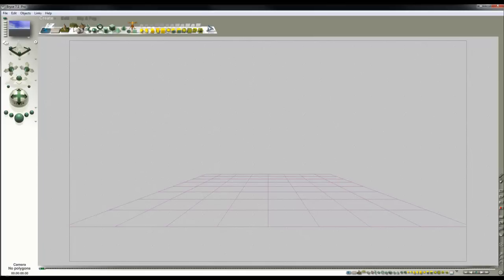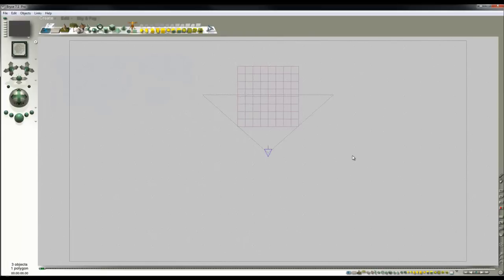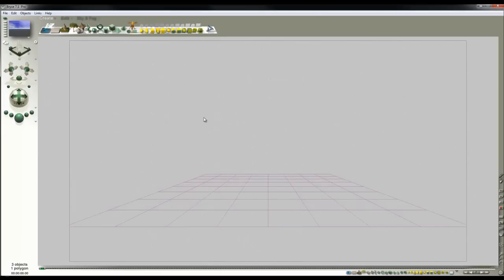Now, if I switch to the overhead view in Bryce, you see I've got an infinite plane and the camera, which is facing north. Now, the anisotropic feature is driven by a vector determined by a colour, RGB values providing a different strength of the vector. So orientation of the camera might be significant. The feature's a little bit difficult to get working, let's put it that way. I don't know whether it's buggy, I've not tested it enough, but it can be tricky to get working. So I'll show you which direction the camera is facing in, and then if it's a significant factor, you can set it the same.